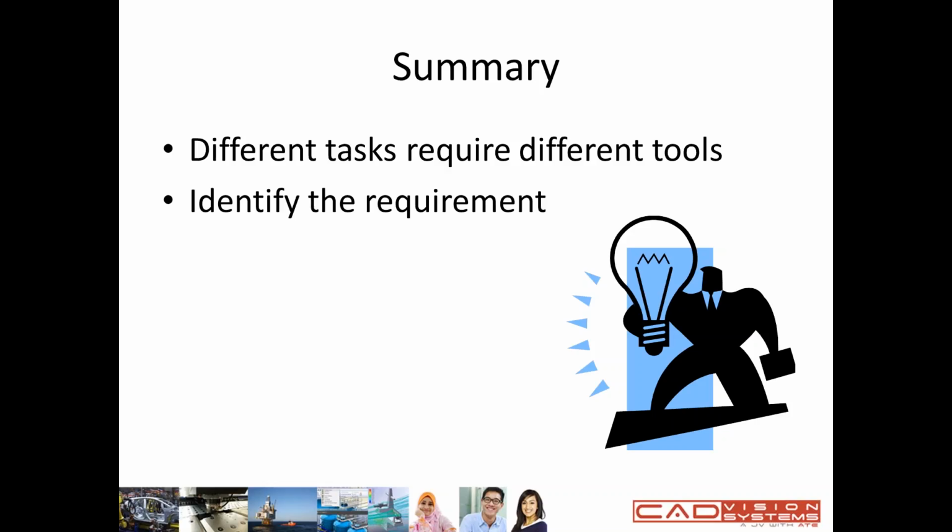SpeedPak you use in, let's say, plant construction or layout or machining that has a very complicated design, where you wish to see the inside without exposing it. And about defeature, when you want to protect your intellectual property, you use defeature. You get simplified detail, and you also fill the cavity.